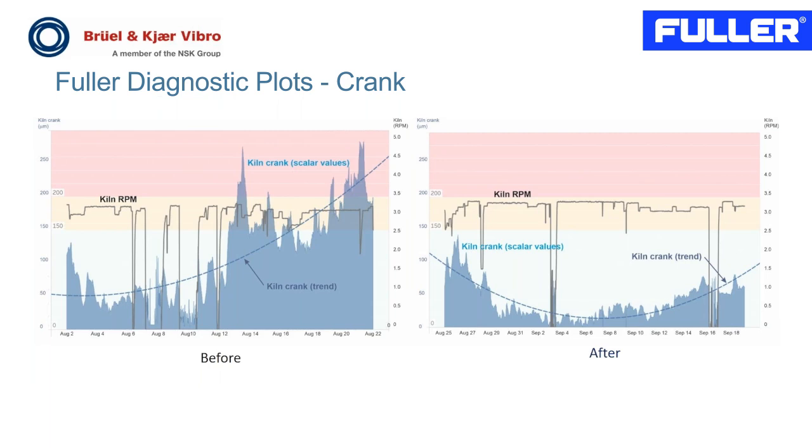But then what we do is monitor and evaluate what I call accumulated damage. This is basically for how long we have had overload and at what value. You could actually see it as the area under the graph, as the integration of the scalar curve, because this accumulated damage is what eventually will lead to fatigue failures in the mechanical components.